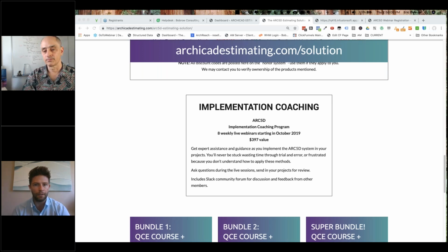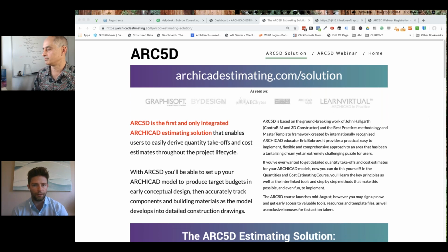That would all be represented by a single unit cost, unless of course you wanted to break it out and track those items separately, as I showed in the resource-based unit cost, where you could plug in a number for material, a specific value for labor, a specific value for equipment, and a markup, and then use an expression to calculate the unit cost considering all those components. So typically labor's included in the number, and the only time it wouldn't be is if you broke it out separately to track it separately.